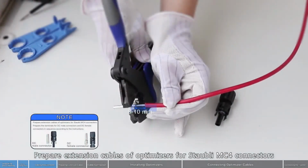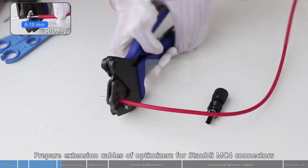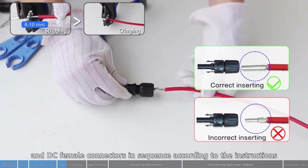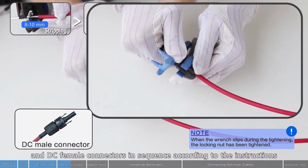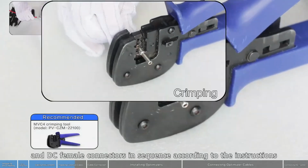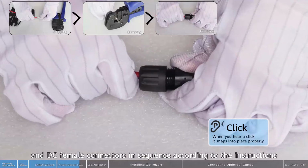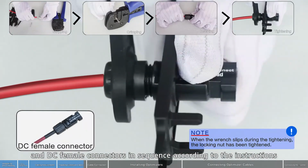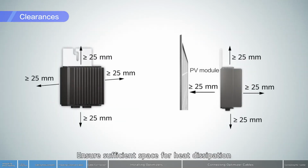Prepare extension cables of optimizers for Staubli MC4 connectors. Prepare the terminals for DC male connectors and DC female connectors in sequence, according to the instructions. Ensure sufficient space for heat dissipation.